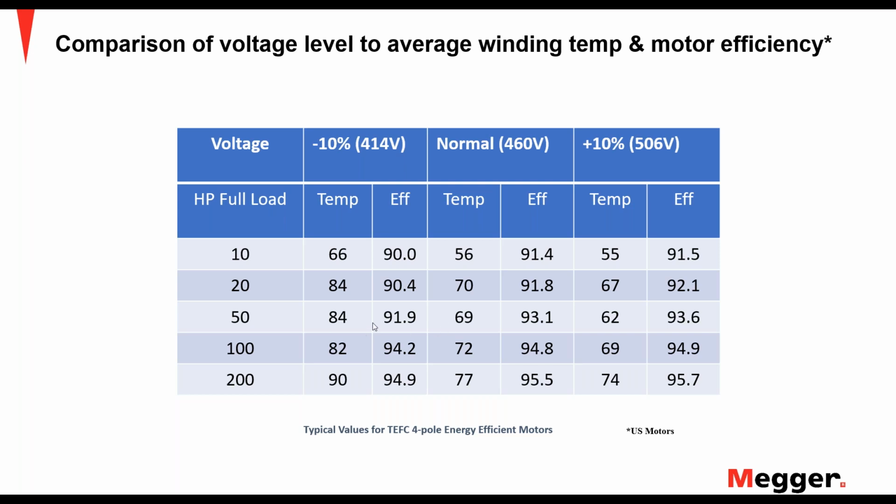We're at 15 volts higher, so we're shortening the life of that motor by doing that. Our efficiency went down, and we're destroying that motor. The heat's going to be attacking that insulation and destroying it.